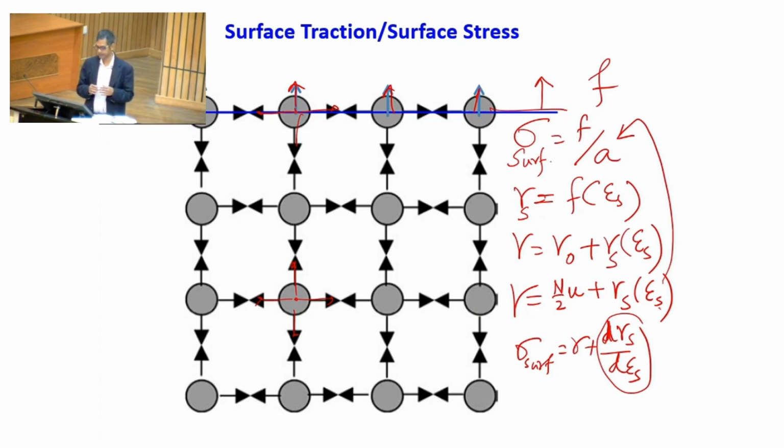So, what can you do? Well, you can actually calculate gamma s if you know the total gamma and if you know the number of bonds broken. But in most cases, it is very difficult to know how many bonds are broken. Bond energy u can be known for a material. Let us talk about graphene actually. You can easily get these things.